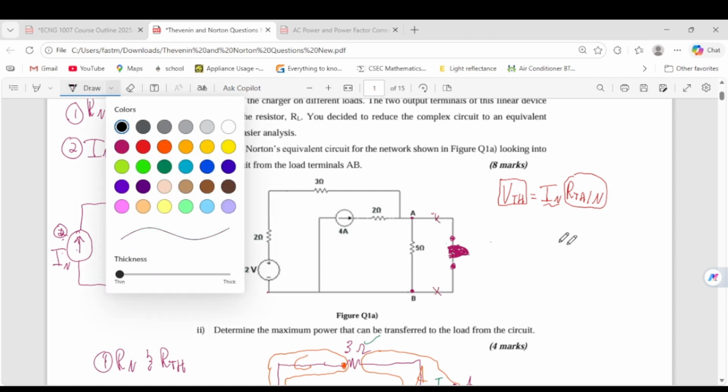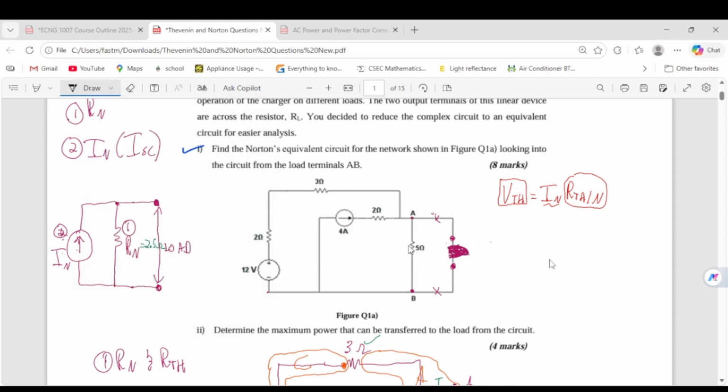So to do nodal analysis, you just have to follow some steps, right? If you're looking at this, the first thing that we have to do is find our reference, which is basically ground. What I do is I look for the bottom node, the biggest one at the bottom. In this case, if you're drawing your nodes first, this entire thing at the bottom here is B. Remember, the node is just bounded between the components. So you just keep drawing until you encapsulate all the components. So this will be ground, and the voltage for ground is 0. Right? So all this here will be at a potential of 0. So that's the first node there.